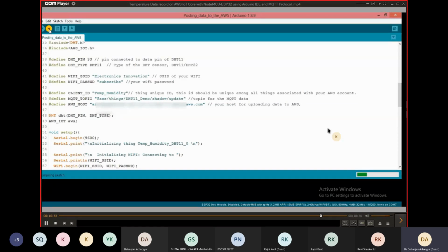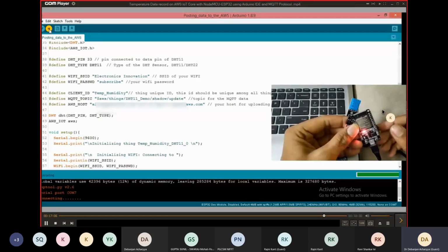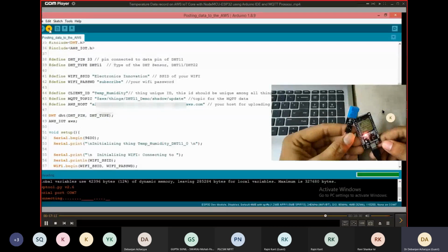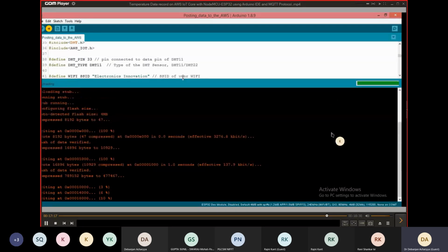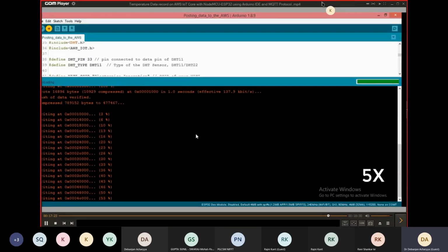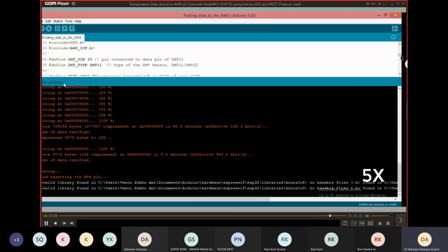First it will compile the sketch, and then it will create a hex file, and then it will upload the sketch there. So while uploading, when you get this connecting, you need to press this boot button once. After that, the uploading will be initiated. And here it is uploading. It will take a few seconds to upload. Here we got done uploading, and now we open the serial monitor.